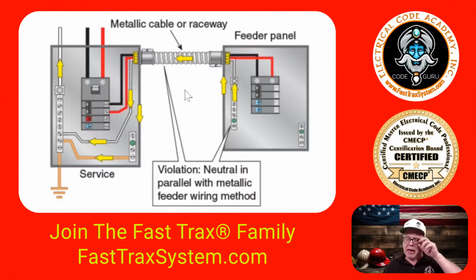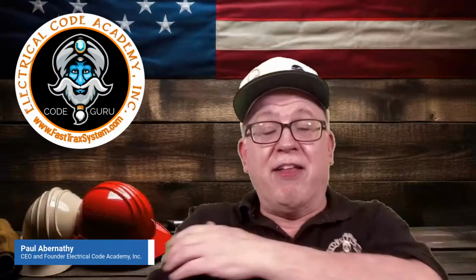All right, so important. You do have some options. I encourage you, if you want to fix this situation, go look at 250.118 and see if the wiring method that you're using actually qualifies as an equipment grounding conductor. If it does, then you remove this screw, isolate this neutral bus, and then you're all good to go. So that's the whole purpose of that illustration.